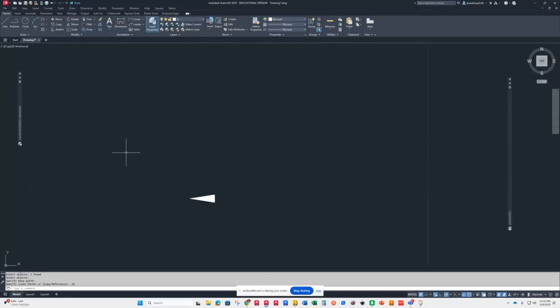Now, in one of my books that I used between this one and the one I started with, that was one of their exercises, and I thought it was really cool. So that's why I show people, hey, you want to know how to make an arrowhead? Here's a cool way to do it. Use your polyline command. So that was using polyline, and then we used p-edit, and then we used scale. So there's like 3 different commands that you've played with right there.